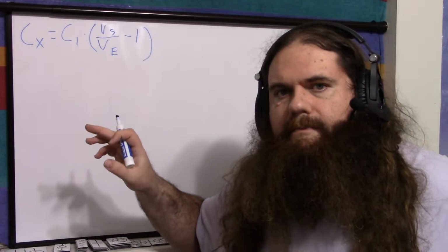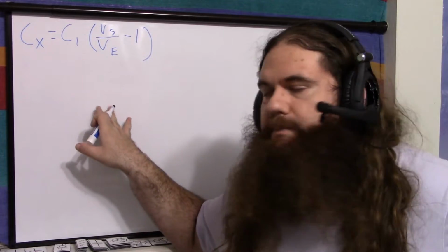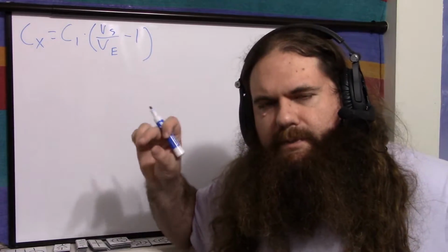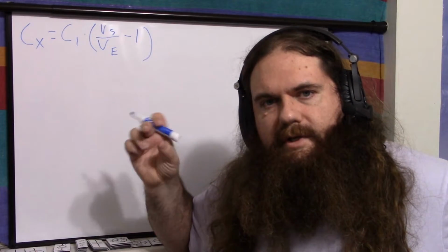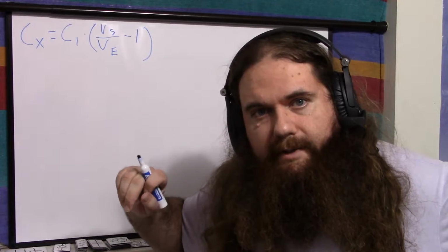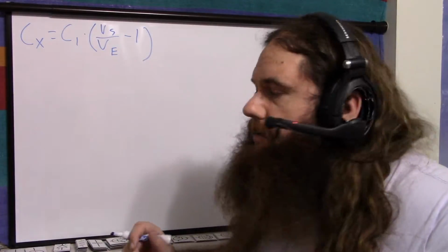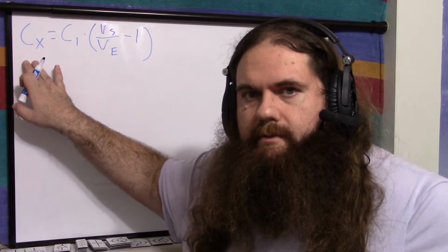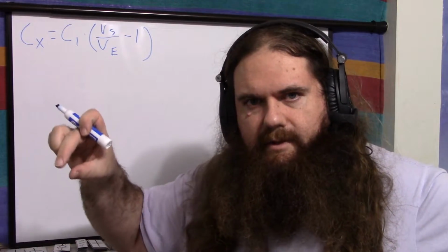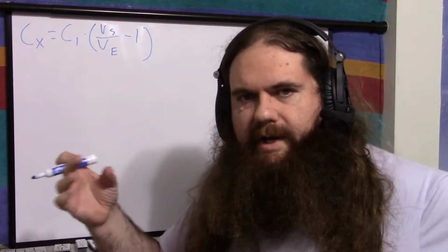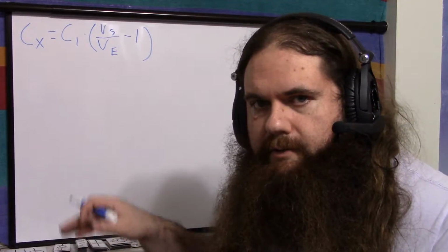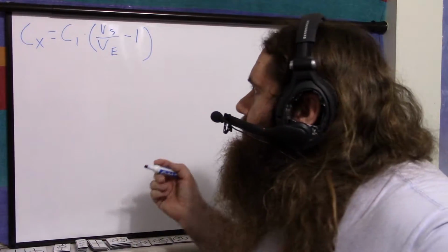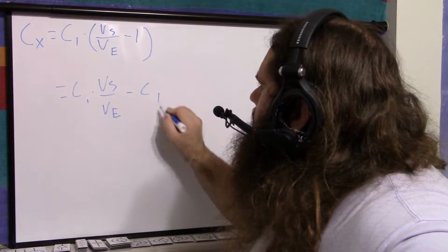So what I'd like to do is calculate the voltage I would expect if there was no variance. If 6.8 microfarads meant 6.8 microfarads, and I want to compare the measurement voltage I get to the voltage I would expect. So to do that, we can just solve back around, because this time we know the capacitance of this, because I'm testing with capacitors I know. I'm just testing this method. So what we want to find is the voltage we expect it to equalize to if these capacitances were exact. So we'll multiply this back out, minus C1.